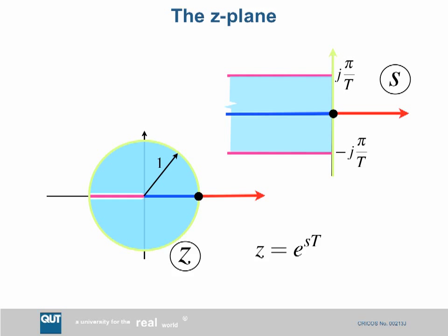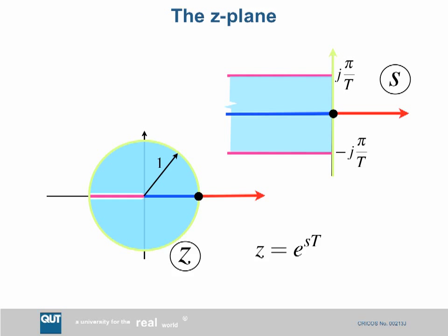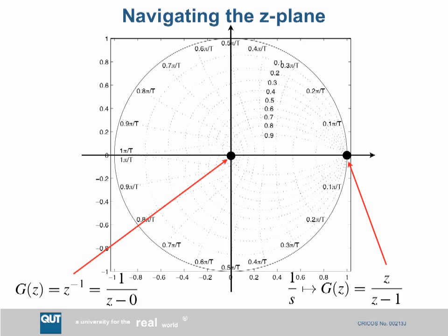They're all color-coded, and that was covered in the last lecture. If we consider the poles and zeros, we can map them from the S plane to the Z plane. And if they're stable, they live inside the unit circle. Now, if we go back here again, we see that the unit inside the unit circle corresponds to the inside of that blue band. On the S plane, it's on the left-hand side of the imaginary axis, therefore it's stable. So stable poles must be inside the unit circle.